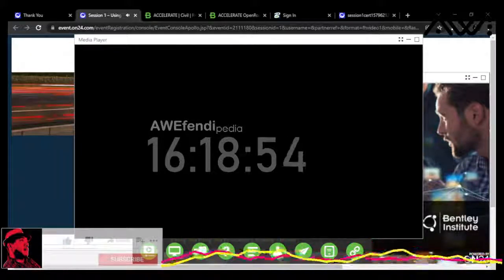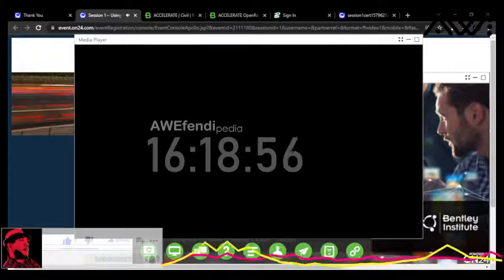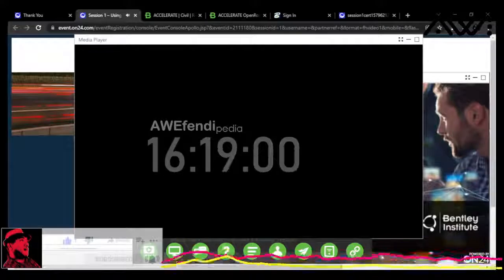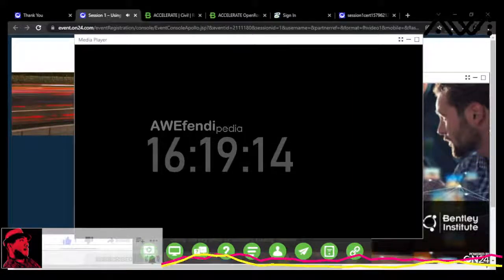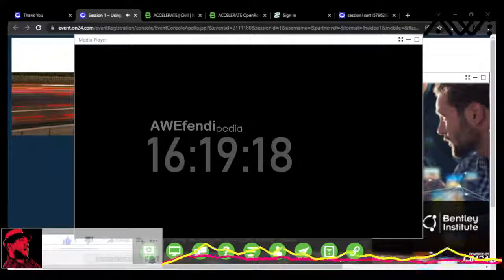So what I'm going to do over here is add a start code to this point here and just start a new string. So I've clicked on the point, going to go to properties, and in the link code, I'm going to add a start code for that. Remember, all of my features are still being drawn using those link codes. So there, that ended the string on the left side of the bank, and it started the string on the right side of the bank.